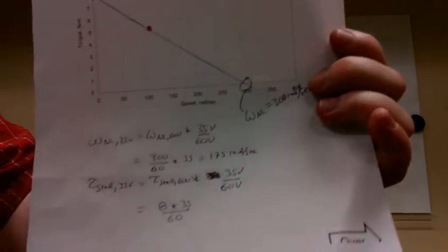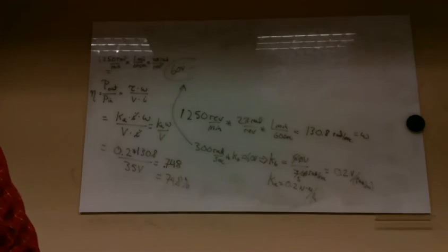So that's actually 8 times 35 over 60. 8 times 35, 240 plus another 40, 280 over 60, 28 over 6. Let's see. 8 enter 35 times 60 divided by... 4.67 newton meters. Alright, there we go. So that's the stall torque.